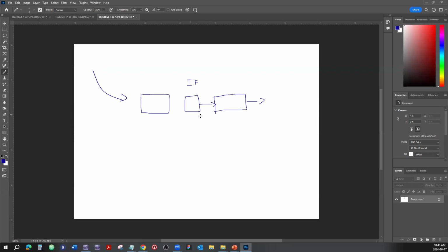You don't need this amplifier to handle all the high frequencies that are coming and hitting it, because whatever station is being translated, the carrier is being changed from whatever it is to the 455 kilohertz, and from that the carrier is nicely stripped away.